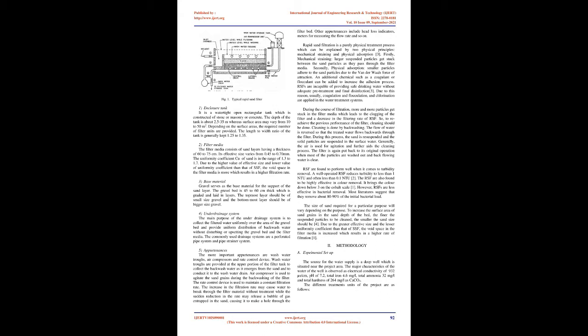RSF quickly gained popularity due to its less land requirement and high filtration rate. Due to the greater effective size and the lesser uniformity coefficient than that of SSF, the void space in the filter media is increased, which results in a higher rate of filtration.